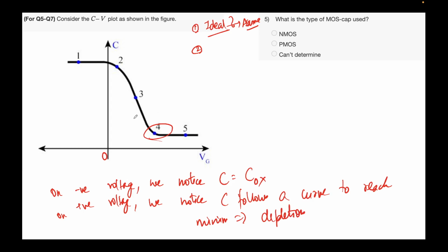What type of semiconductor will deplete on application of a positive bias? Let's do that. So this is metal, this is your oxide, this is a semiconductor. I'm applying a positive bias here, right? If we have holes here, they'll get repelled and you'll form a depletion region. If it were N type and you apply positive bias, the electrons would get accumulated, right? That's not what's happening. Only when it's a P type semiconductor, the holes will get repelled away and you will form a depletion region.